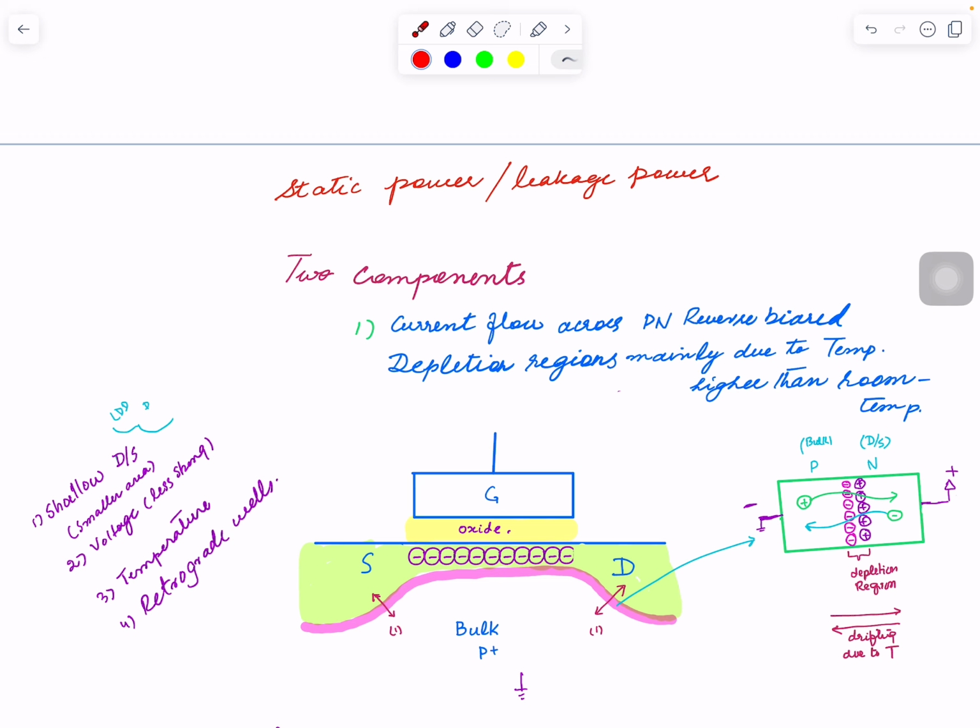Okay, temperature, yes. If we can somehow make this device cooler, so it doesn't get a lot of temperature here, then this leakage current will be less. Okay, great. Something else you can think of? The higher the reverse voltage here, the stronger this voltage, we will disturb this area. Okay, it will really push these guys.